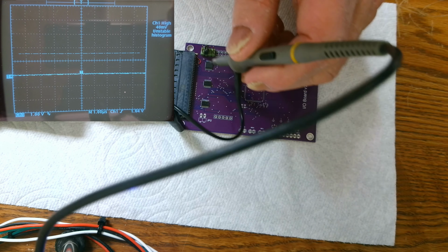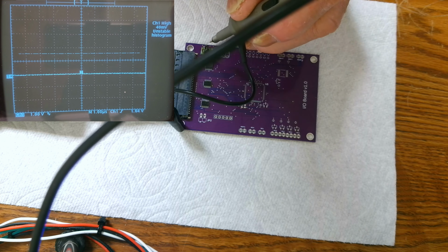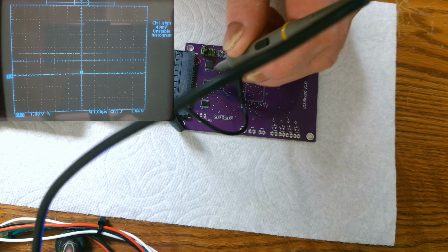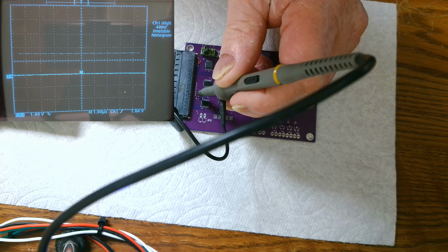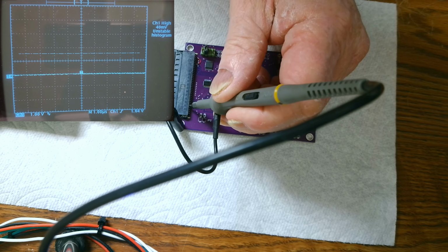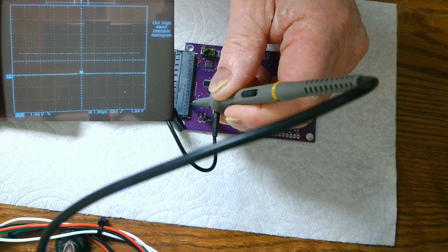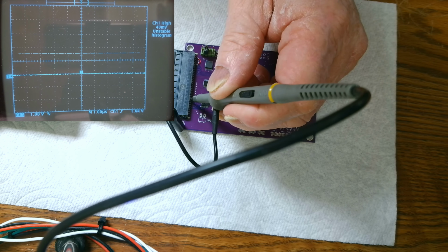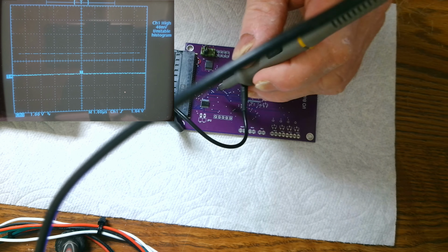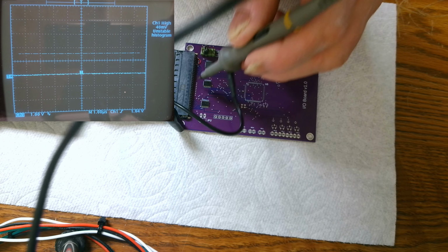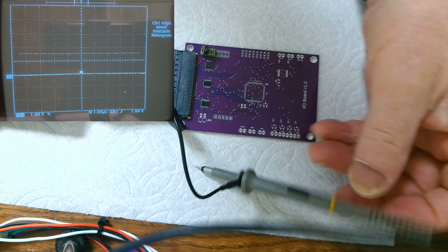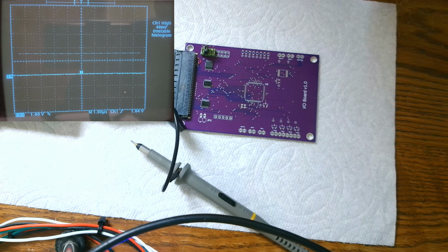So that's making the chips' address select signal high now. So that should put these at a high impedance state. We don't have anything hooked to that. So let's check out one of these here. It's still low. That one's supposed to be all low. So let's look at our schematic and get some address lines measured and see what's up with the address lines.